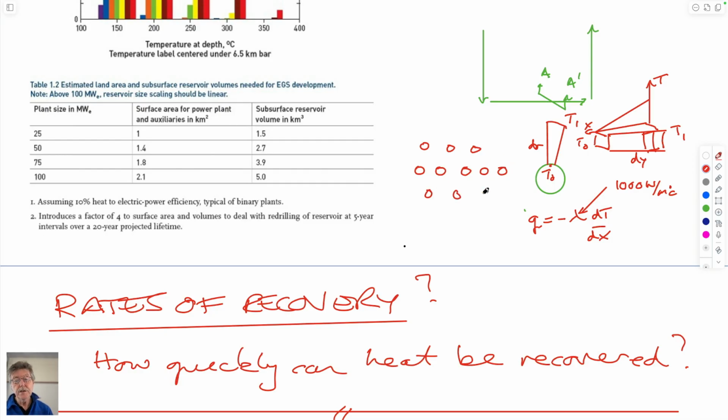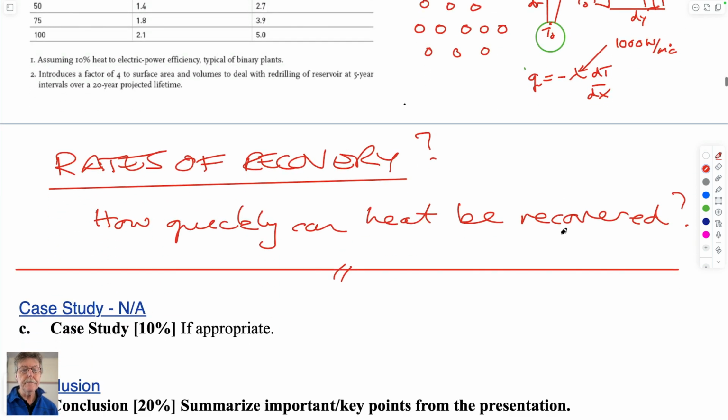And so these individually would only get a small amount of conduction to themselves, but if you sum all of them, then all of a sudden it becomes a large number, because instead of just one of these, you have 10 or 100. So that's the only way that you can make that system work, because intrinsically the rate at which you can gather heat to this pipe is controlled by conduction, not by convection as in other subsurface geothermal systems. Okay. All right, so I will stop there.